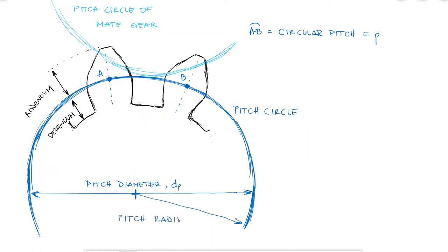just the pitch radius. So every time we refer to the diameter of a gear to talk about the relationship between number of teeth, angular velocity, or torque, we will be using this pitch diameter. The circular pitch, that distance between one tooth and the next, will for this reason be equal to the circumference divided by the number of teeth.